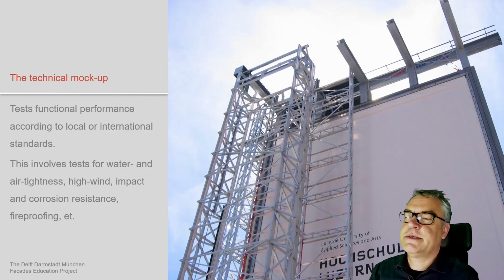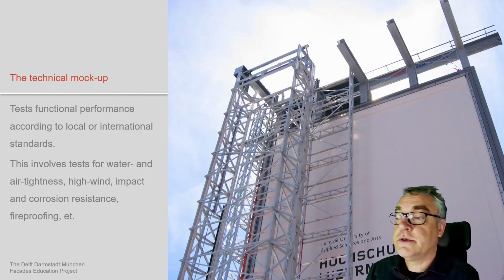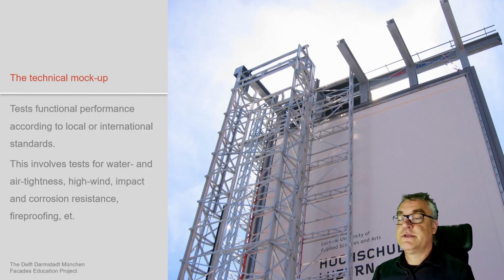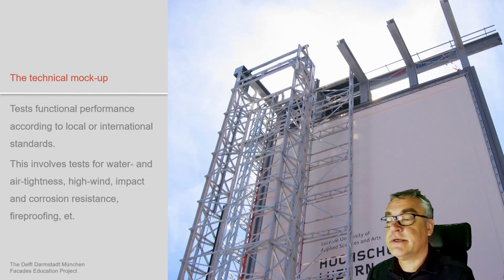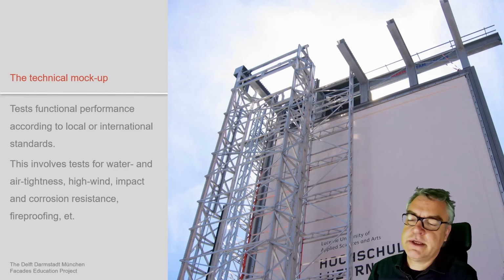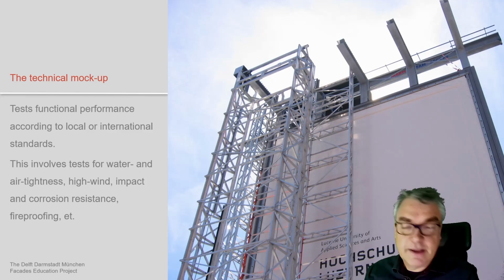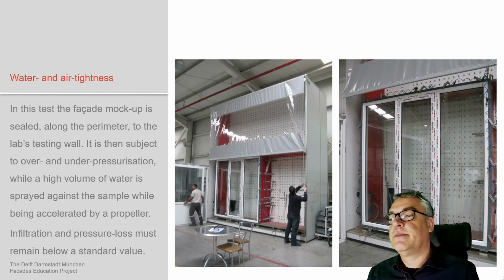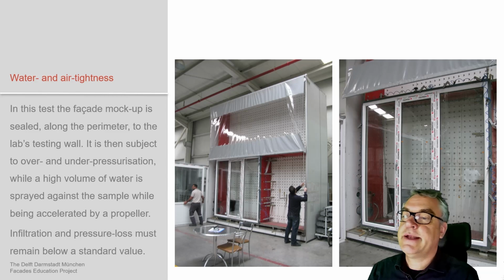A technical mock-up tests functional performance according to local and international standards. This involves tests for water, airtightness, high wind impact, and corrosion resistance, as well as fireproofing. We're going to see all of them in some samples. Water and airtightness.